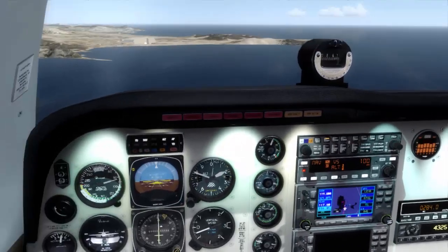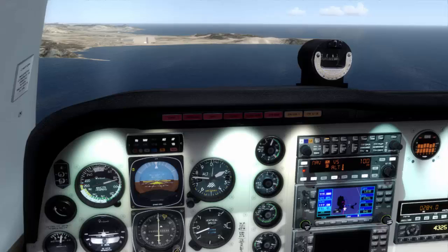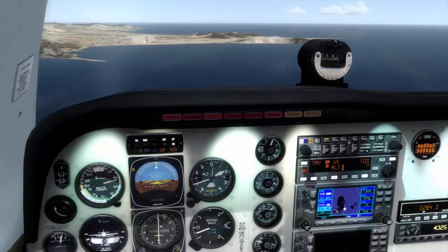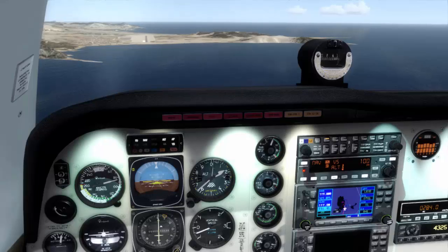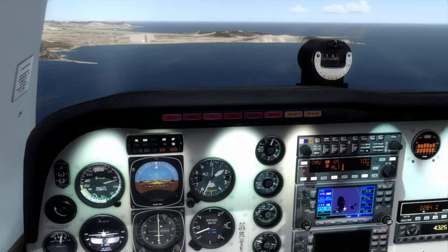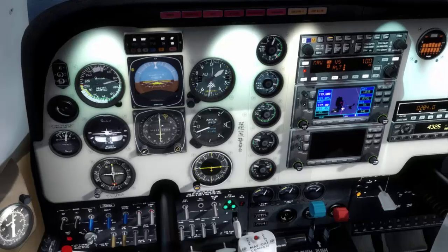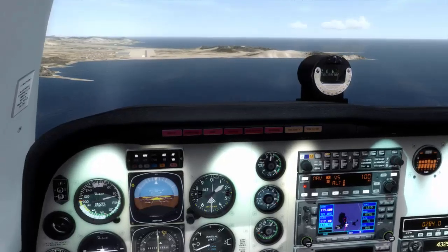And we will be taking a look also to the GPS to know the distance we are from the IBIZA VOR, okay? Because when we reach 2 nautical miles from the IBIZA VOR, we will have reached the MAP, the missed approach point, and at that point we will decide if we continue and then we land, or if we don't see the runway because we have a lot of fog or something like that, or we have extremely bad weather conditions, then we will have to decide if we miss the approach, okay?